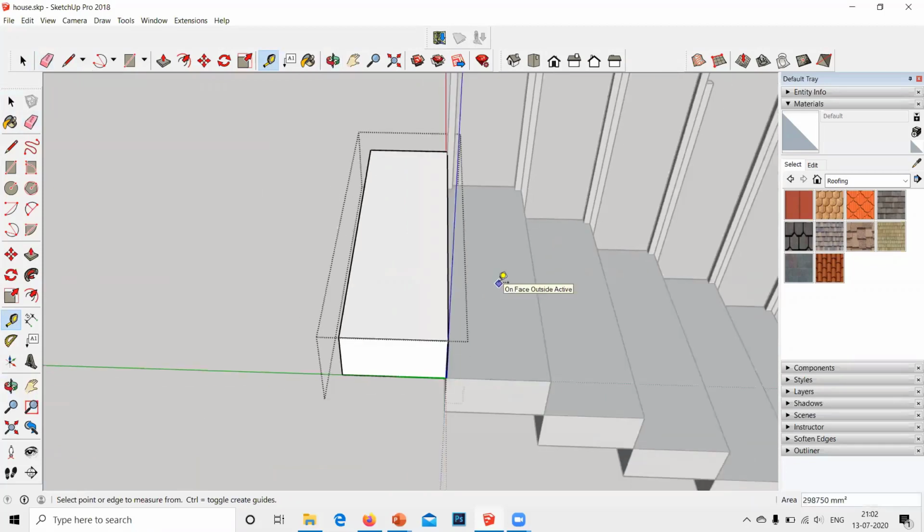Third click. I want it to be 1000, 1000, and you have a square. Rotate the whole thing. Use this. Now this is your staircase. It looks nice. Tape measure tool. Select the whole thing, enter your left arrow key, endpoint, and enter 1000.